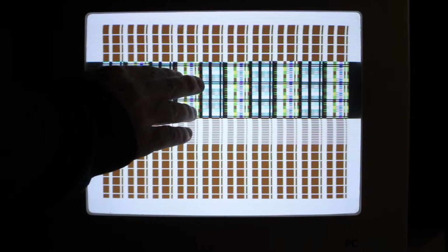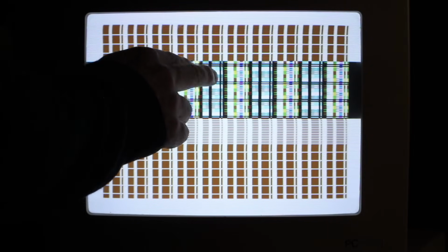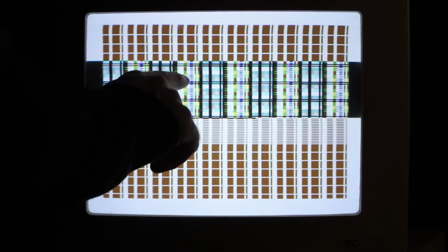But one thing you could do is do things a little faster. It's actually quite fiddly to do bit twiddling to set individual pixels, and essentially what you have to do when you change the color is change a certain register in the chip, and that is really time consuming if you want to do it pixel by pixel.